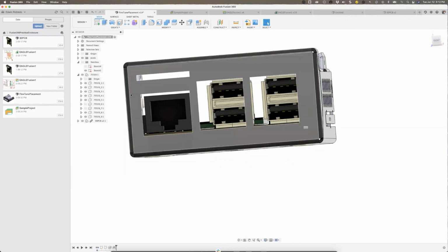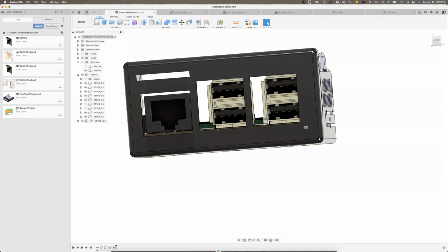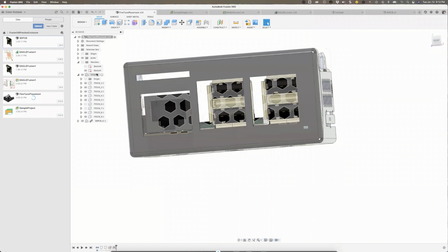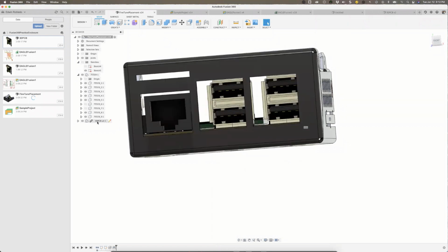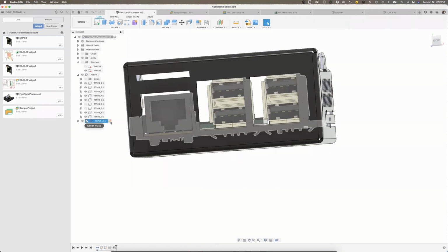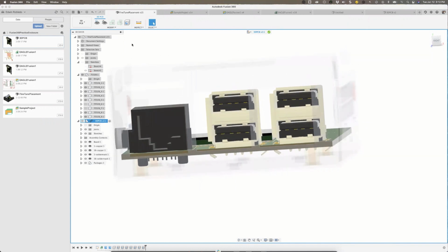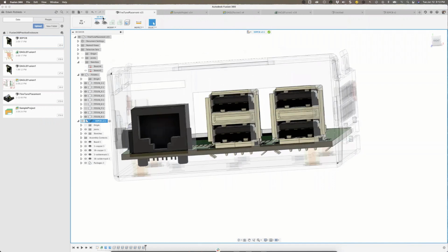But right now, the way you accomplish this is I'm going to save what I've done so far. And I'm just going to select here where it says, this is the PCB. This is the one. And you'll notice that the pencil shows up right here. It says edit in place. I'm going to select edit in place. Give it a minute. It takes a minute to catch up. There it goes. When you see it goes in that wireframe format, now I'm in the 3D PCB mode.